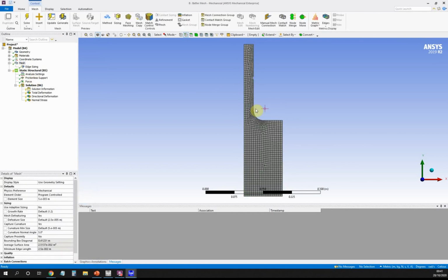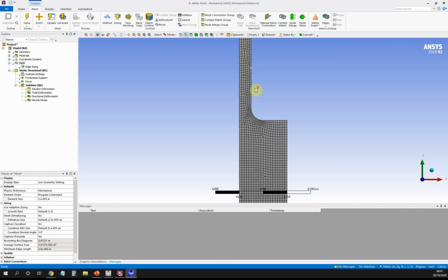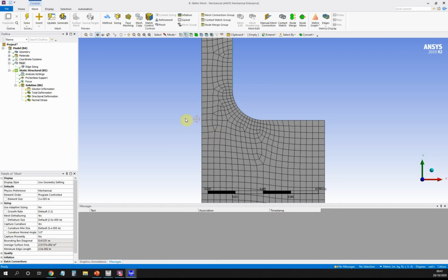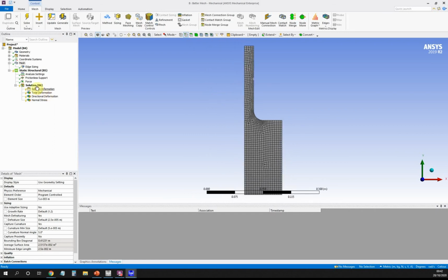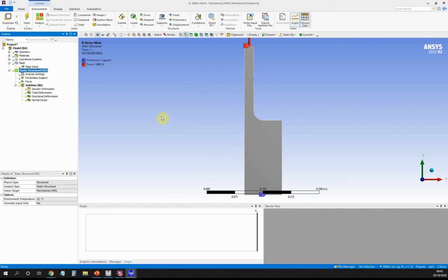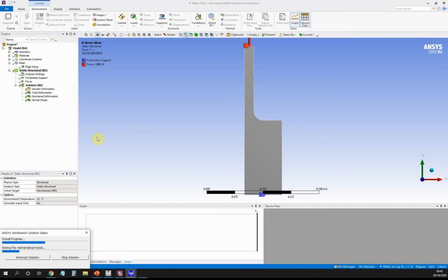So you'll see now, if you compare this side to that side, for example, you can see that I've gotten much more divisions here. So these ones are all the same size, and they're closer in size to the ones around the curve than the old size would have been like this. So again, let's just have a zoom in just to see what I'm talking about. So again, the old element size would have been that over here. So these ones are about maybe 2/3 of that. You can see they're closer to what I want to get to in there. Okay, so we'll just see if this has made any difference. Again, we'll just do another solve, and we'll probably leave it at this one. Not expecting too much of a difference.